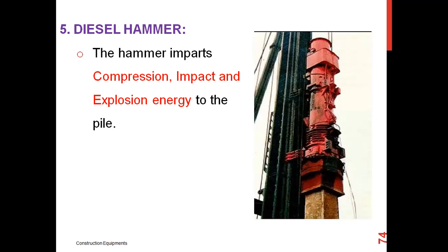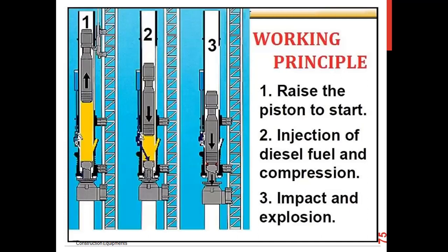The diesel hammer. This diesel hammer imparts compression, impact, and explosion energy to the pile. Here is the working principle of these hammers: the rise of the piston to start. Here you can observe the rise of the piston, the injection of diesel fuel and compression here, and impact and explosion can be seen in this image.